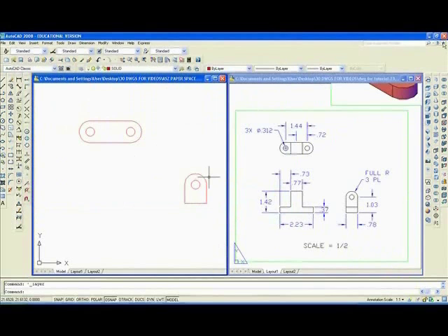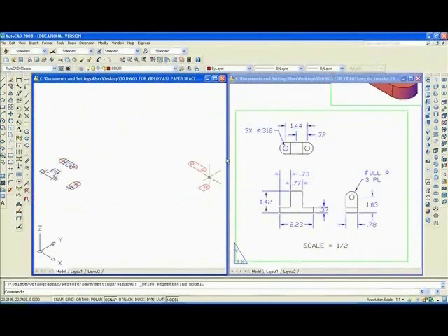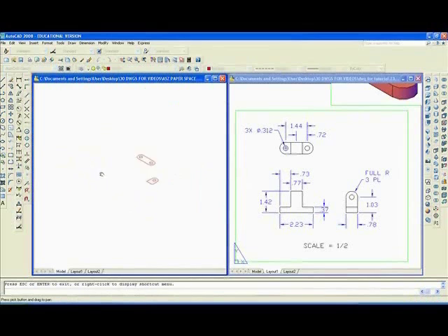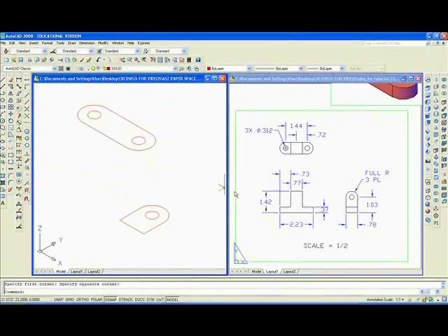And then we're going into this southeast isometric. As I said, I can put the dimensions on later. I'll pan over here like that and enlarge this view. And I can type EXT, enter, to extrude everything here to a height of 0.37.